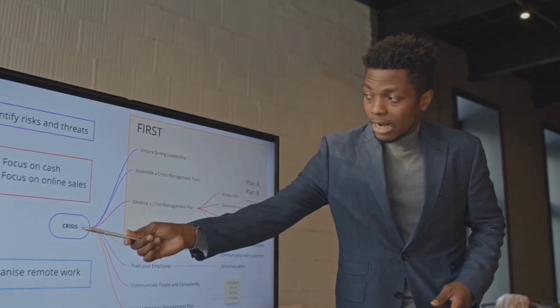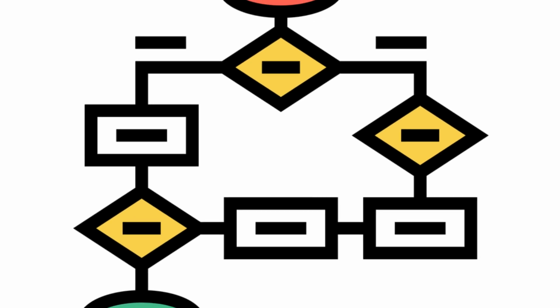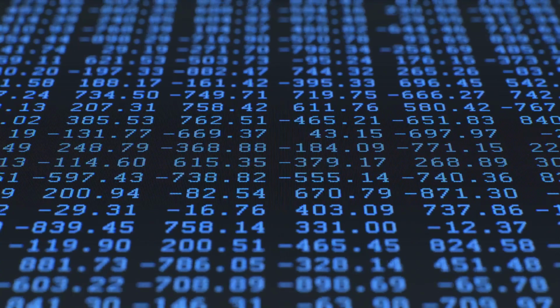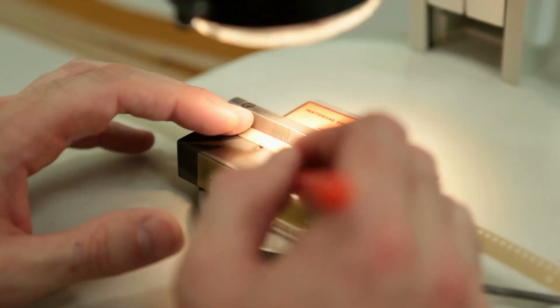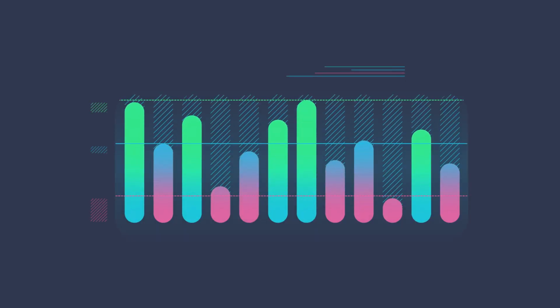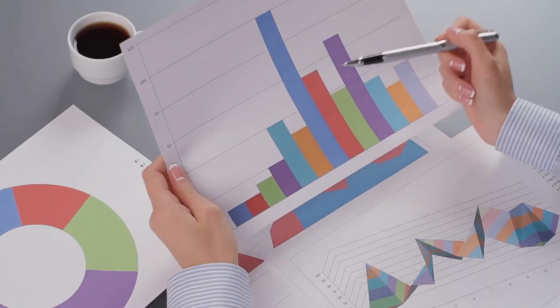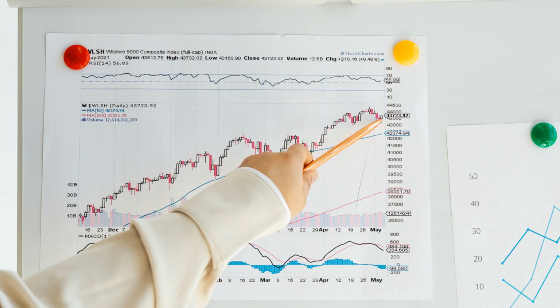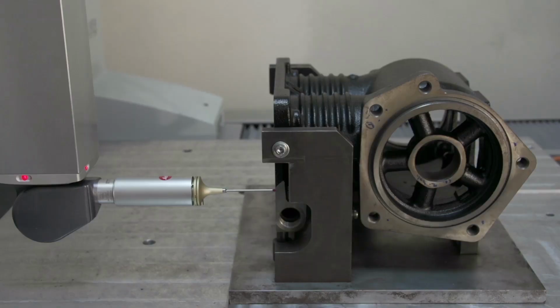Choosing the right control chart is simple if you follow a logical path. First, are you measuring continuous data or counting attribute data? For continuous data, if you collect in small groups, use X-bar and R. For larger groups, use X-bar and S. For single measurements, use I-MR.